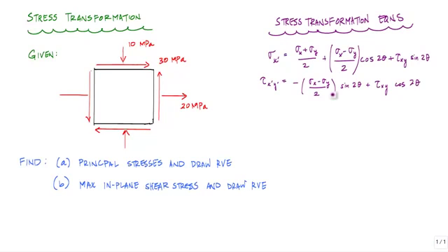We're going to do stress transformation without Mohr circle, and that means we're going to use stress transformation equations, which I'll write out over here. Hopefully you've seen equations like this and how they were derived. Normally these equations are derived, or at least this set is based on starting out with a plane stress element whose horizontal axis is defined as theta equals 0 degrees, or some other axis is defined as theta equals 0 degrees, and then going at a new angle theta rotated counterclockwise. So this would define our x prime and our x axes. The y and the y prime axes would be perpendicular to their respective, prime or no prime states.